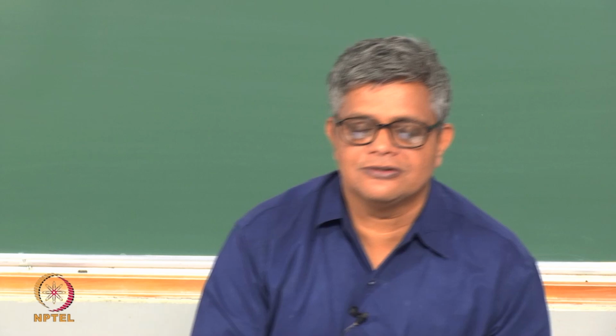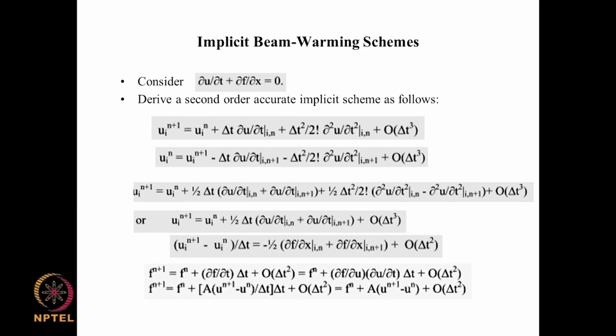So, that is what we are trying to do here. We are looking at an alternative to the explicit McCormack scheme. There is also an implicit McCormack scheme, but we would like to examine this implicit Beam-Warming method, which has also proved to be a successful method and which employs a different way of taking account of nonlinearity, which enables us to get around this limitation of delta t arising in boundary layer type of calculations where delta y is small.